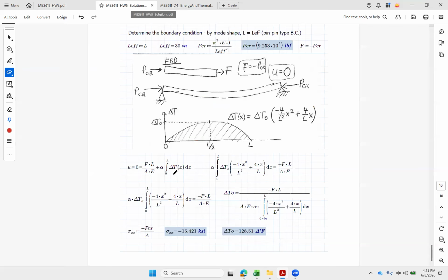Now, right at the onset, when it's about to buckle, I can see that my axial stress is going to be pretty high. 925,000 pounds is a lot of force, even for a thick steel plate. We see that comes out at 15 KSI. So maybe, depending on your deck material, that could be a third of yield or a fifth of the way toward yield. But it's a significant number anytime you get up into the tens of thousands of PSI. And compressive.